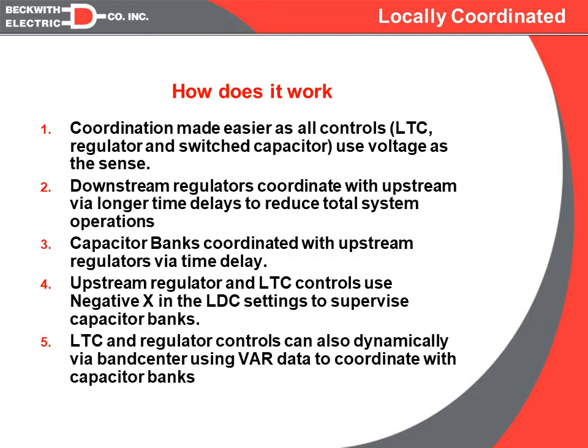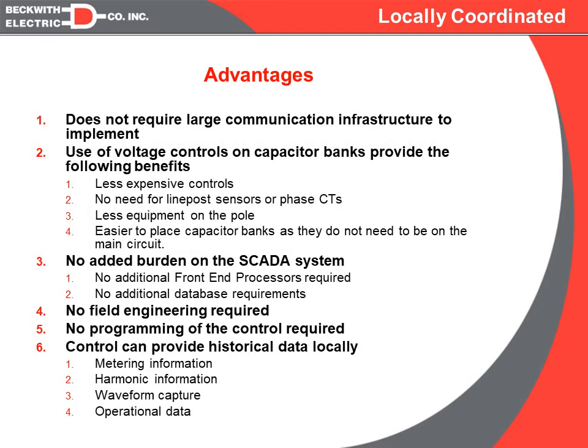That way the regulators, LTCs, and capacitors are all looking at the same sense, which is voltage, to make a decision. And because we want the capacitor banks to take on the operations, we would want the capacitor banks to have shorter time delays than both the regulators and the LTCs. But there's got to be a way of having the LTCs and regulators coordinate the capacitor banks in such a way that we don't get too many capacitor banks on and go too far leading. And all that will be discussed, as I said, in a future session in more detail.